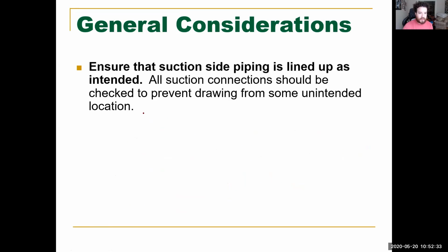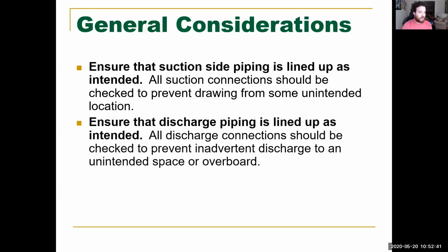So ensure the suction side piping is lined up as intended. Wherever you want to come from, make sure that's open. Wherever you don't want to go from, make sure those are closed. All right. And then ensure that the discharge piping is lined up as intended. All right. Just double check. You know, doesn't matter if you did it before lunch. You can have some nut job on your boat that just wants to get rid of you. He doesn't care how. Just double check everything.